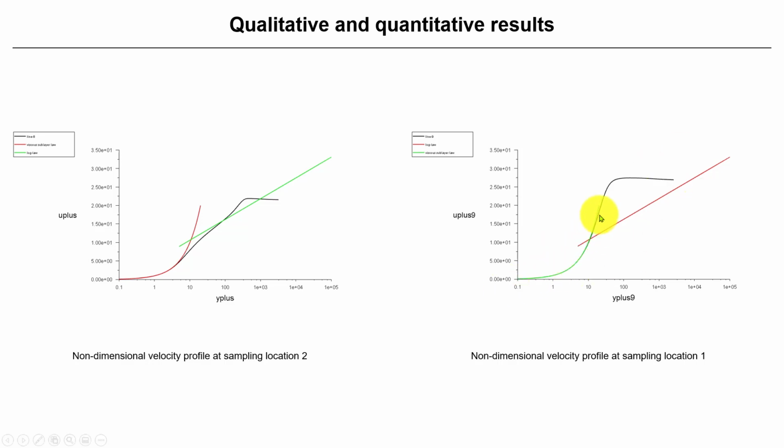You can also get this behavior, for instance, when you have flow separation. But remember, flow separation will not necessarily translate into lower drag, because you have form drag. Here this is skin friction, so this translates directly into lower skin friction drag because we don't have any separation.